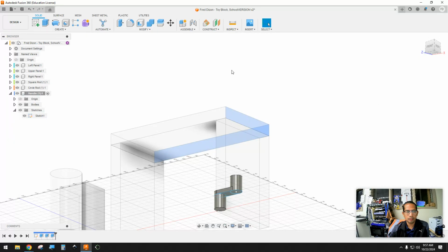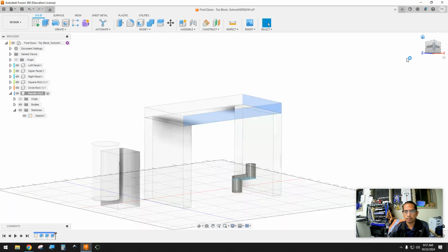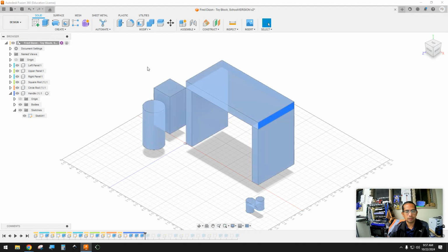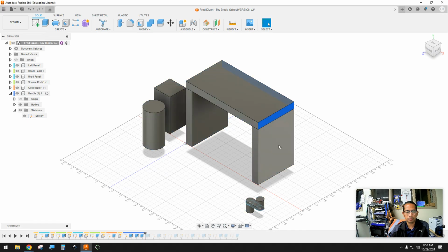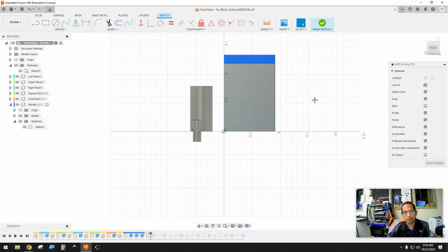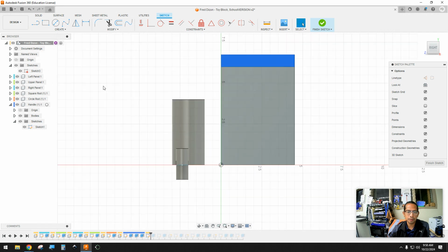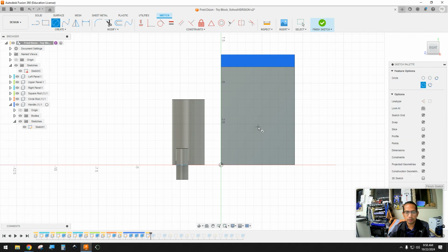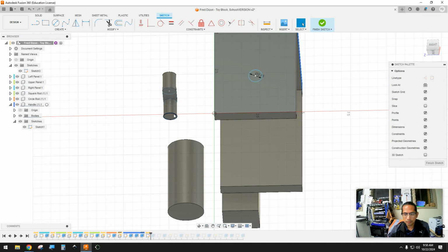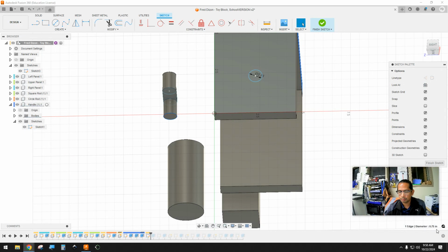Alright. And then click on Home. We want everything to be visible. So let's click on here, a little dot. Oh, we have to put the hole here. So let's go ahead and do that. Create sketch, and click on this face. We don't have to create a component because we're going to modify the right panel. We're going to put a circle here. I believe that circle is 0.75. Might be wrong, let me just check. Oh, it is 0.75 right there.